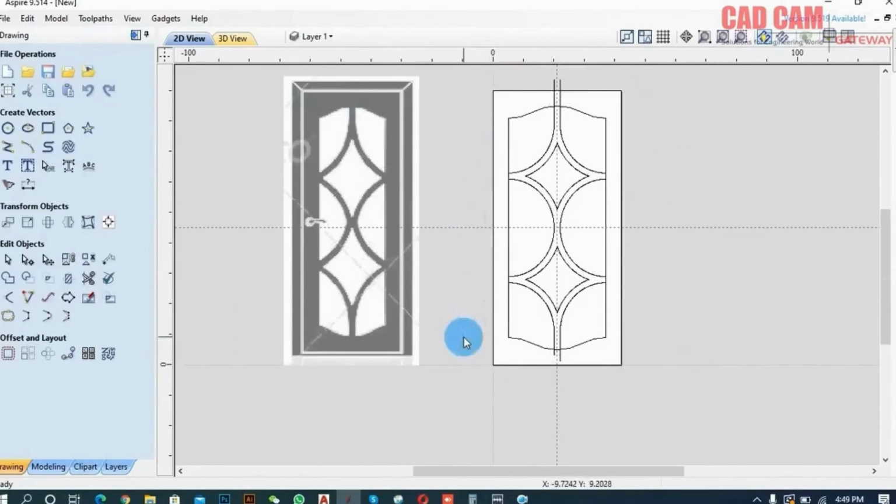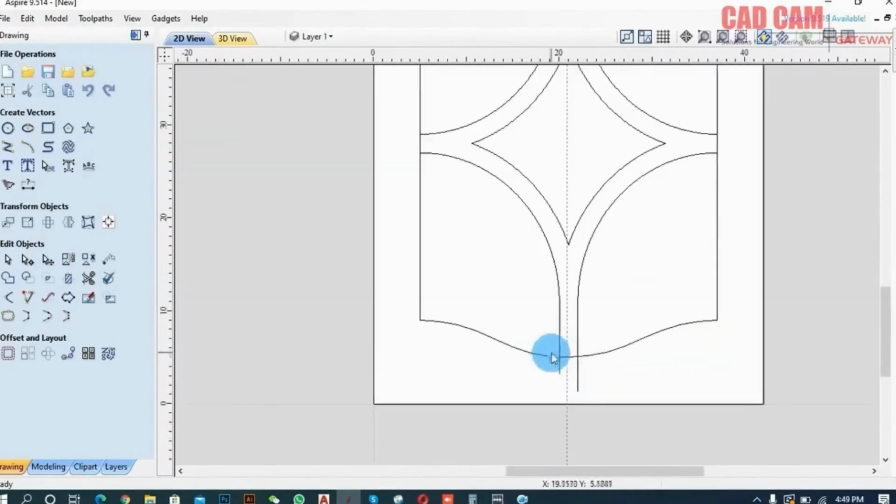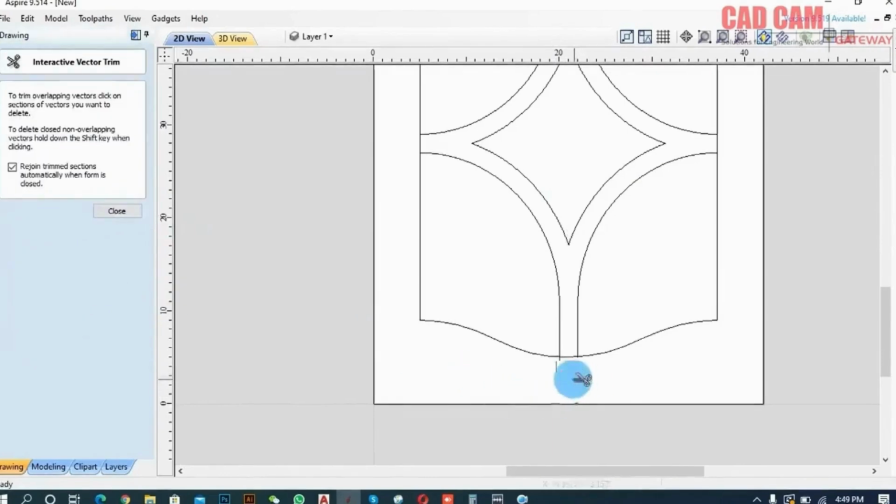We did it in our own way, meaning I backed it up and threw it out, adapting to the situation. Use the trim command and trim these two lines together, ensuring a clean finish. Okay, look here. We also need to trim these, maintaining the integrity of the design.